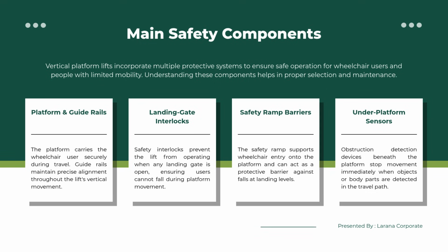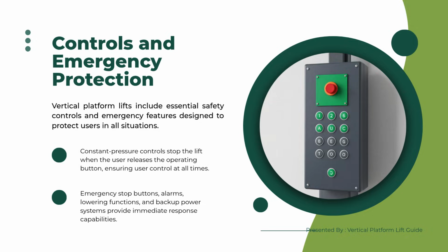5. Indoor or outdoor retrofit. Sometimes the most important decision is not hydraulic versus traction. It is whether the elevator should be installed inside or outside the building. An indoor elevator can integrate directly with the building and provide natural weather protection, but it may require more interior construction and reduce usable floor area.